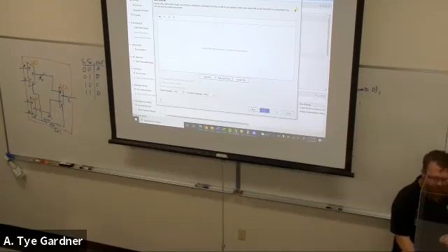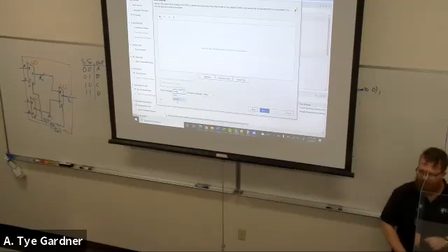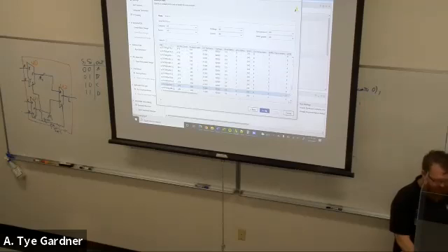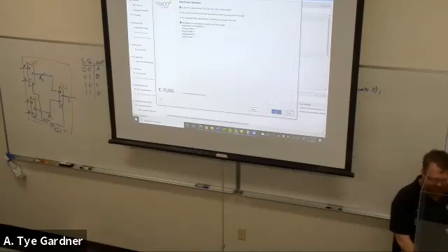You want to make sure down here on the left that your language is VHDL. Verilog is the other super popular language, but we use VHDL. Constraints I'll get to later. This is the part, what device am I programming? You don't need to worry about that just yet, so you can hit next on any of them and hit finish.